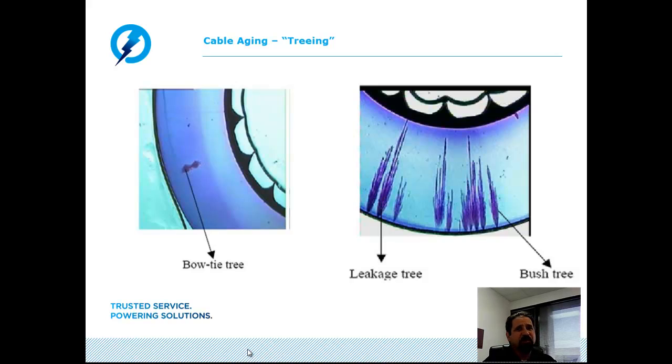It is perhaps the worst degradation process of a polymeric insulation that contributes to the failure of the cable. Water trees are formed and grow in the presence of moisture, impurities, or contamination and electric field over time. There are generally two types of water trees, namely the bow tie and the vented tree.